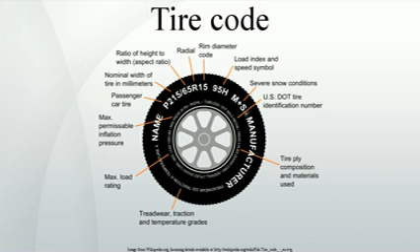Outside of asymmetric tires. TWI, tread wear indicator: a device, such as a triangle or a small Michelin man icon, located where the tread meets the sidewall. It indicates the location of the raised wear bars in between the tire tread channels. LL, light load: tires for light usage and loads. SL, standard load: tire for normal usage and loads. XL, extra load: a tire that allows a higher inflation pressure than a standard load tire, which increases the tire's maximum load. RF, reinforced.